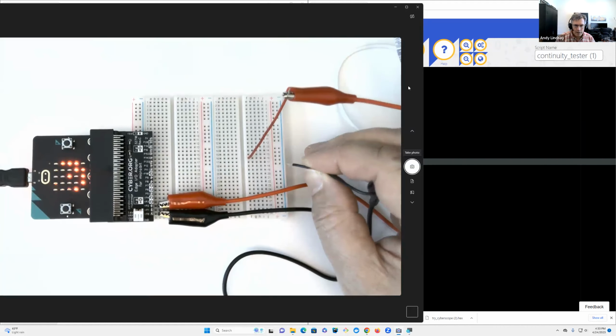But if you switch over so that they're both next to the red line, it doesn't matter where you are vertically, they will be connected. Just as with a row of 5, it doesn't matter which of those 5 sockets you go to, it'll always connect. But if you're even up by one row, it's not connected.